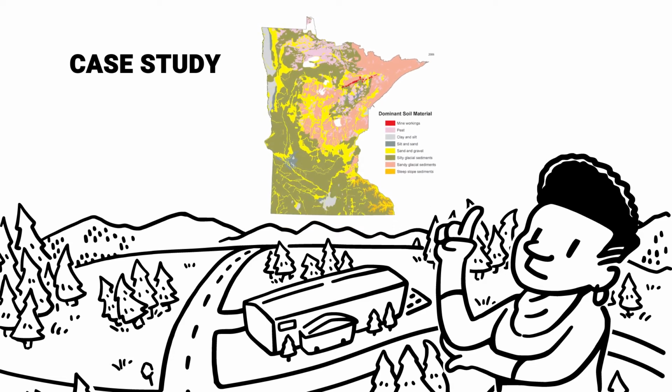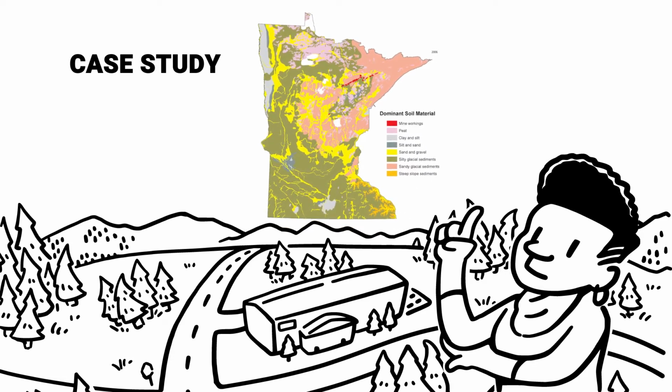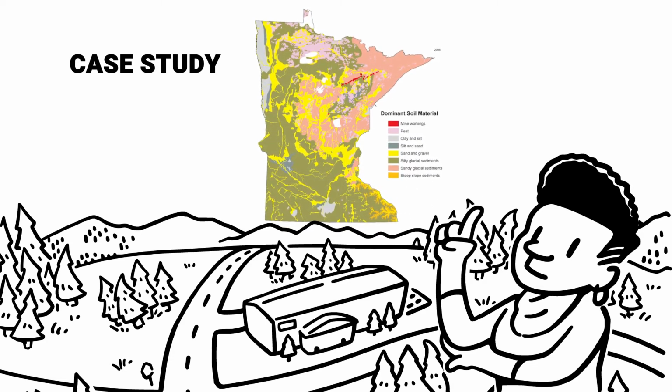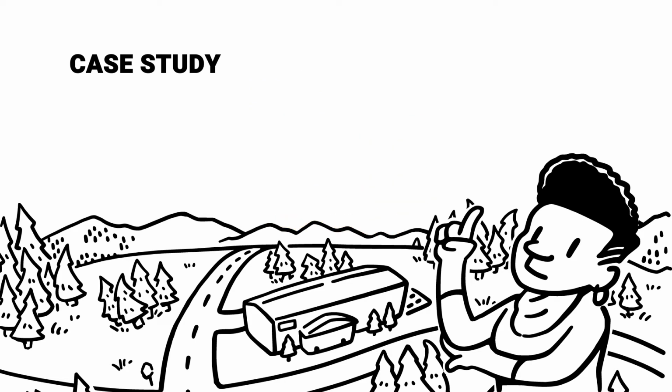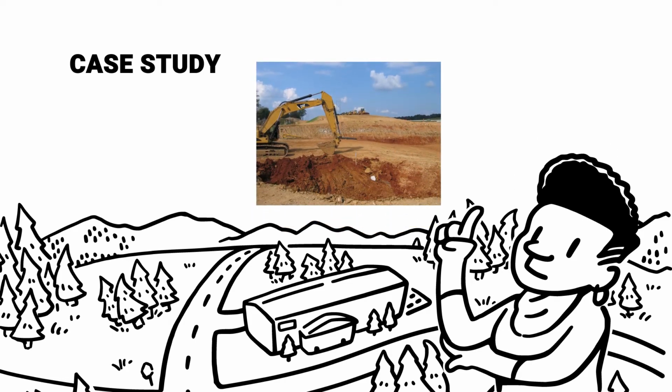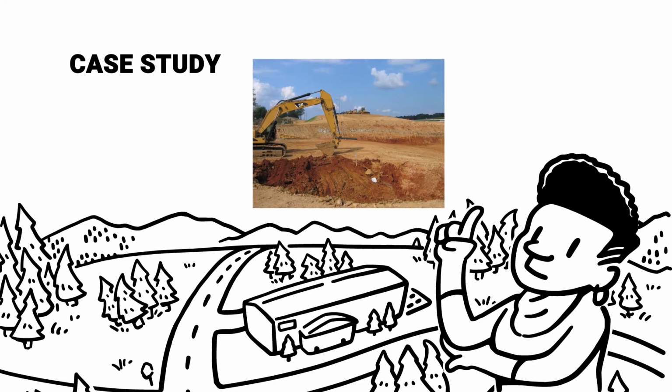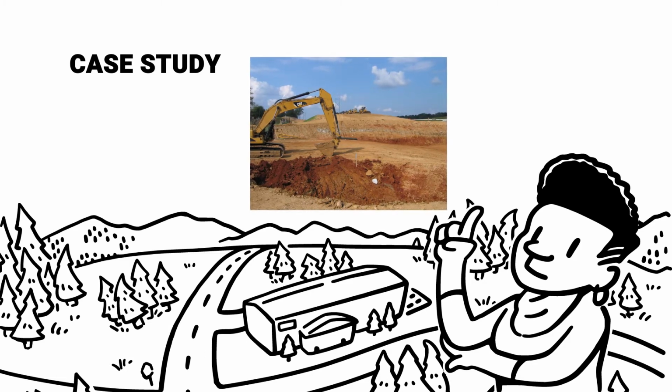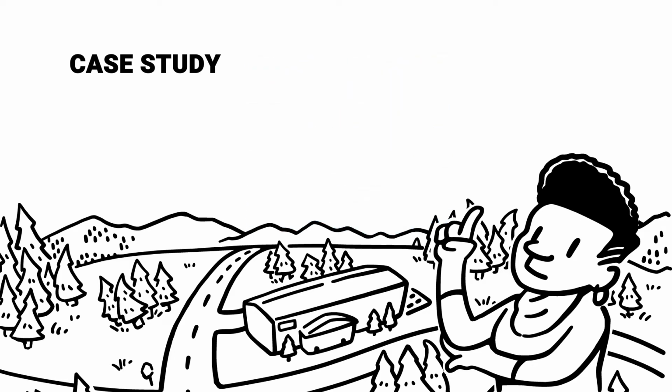We didn't identify any site conditions indicating unique geology or mineralogy. It is especially important to consider unique geology and mineralogy at mining sites, where it can be expected that site-specific background for some metals may be necessary. The scope of the default BTVs identified for our site was any sites within the state. As our site was in that state, this fit within the geographic extent of the background study.